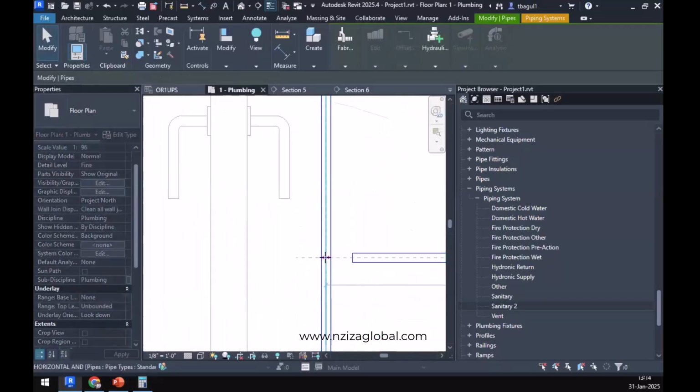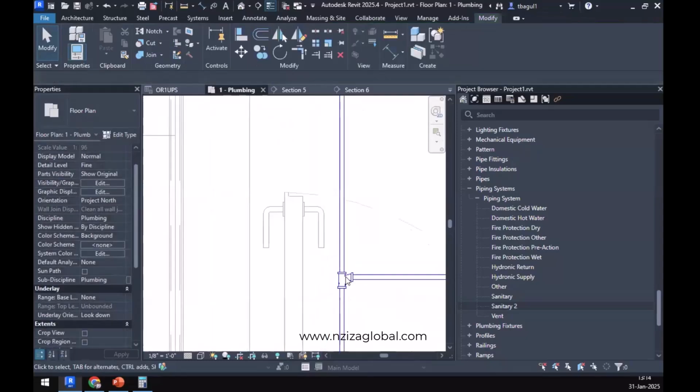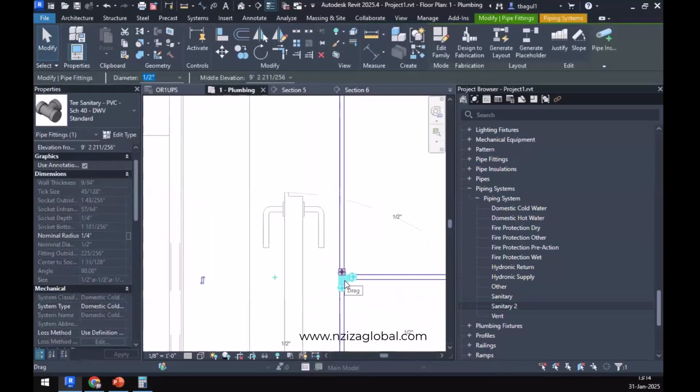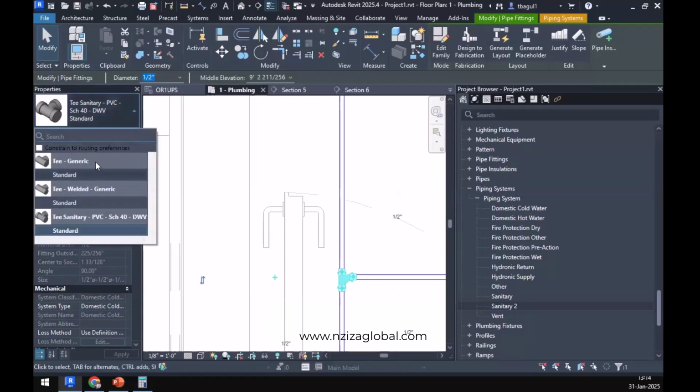Now over here we'll connect it to the pipe. All right, now what is happening is it has taken a Y connection over here as well. But there is no need for a Y connection in a given cold water line. It can be a T directly because there is no suspended solids that are going to get problematic. So you can go ahead and select a, what is going on here?